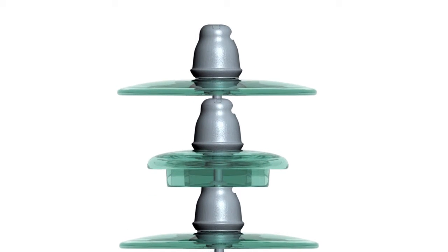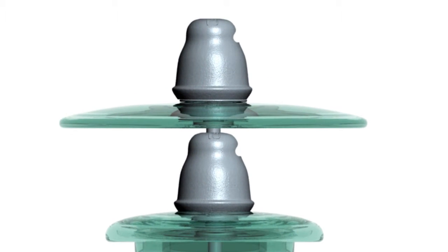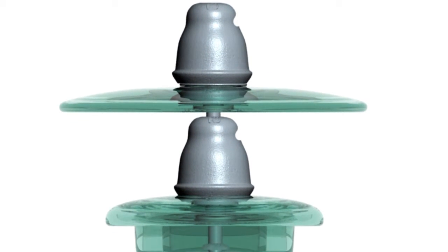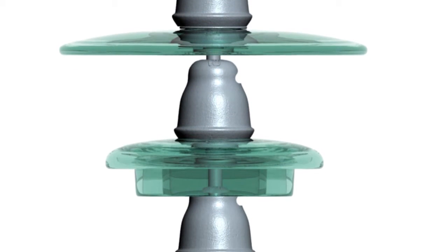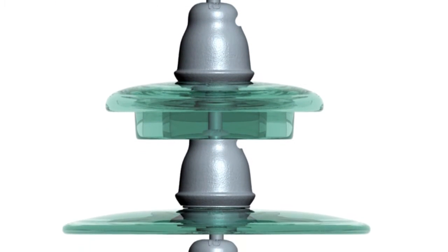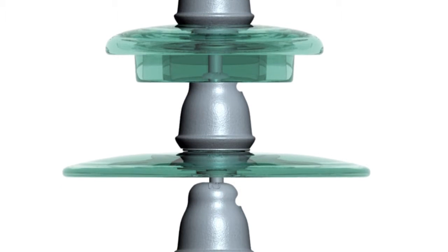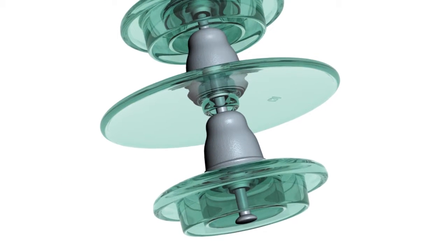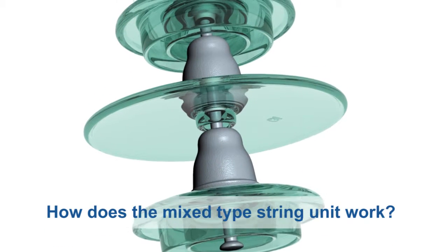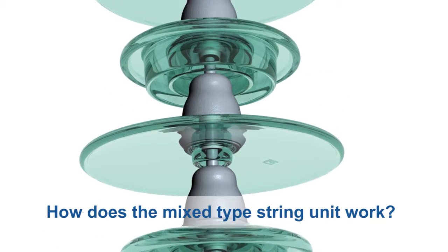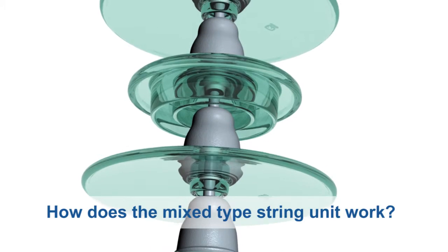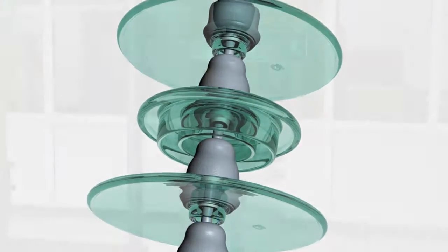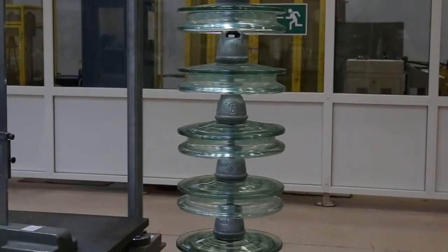To maximize opportunities of the aerodynamic and fog type profiles for mixed contaminations, it is recommended applying string units with interchange of insulators of U120AD and U70BL type. With a uniform interchange of insulating parts of the aerodynamic and fog type profiles, the combination of these parts is superior to the uniform string unit of the PSD type by method of the dirt guard system.